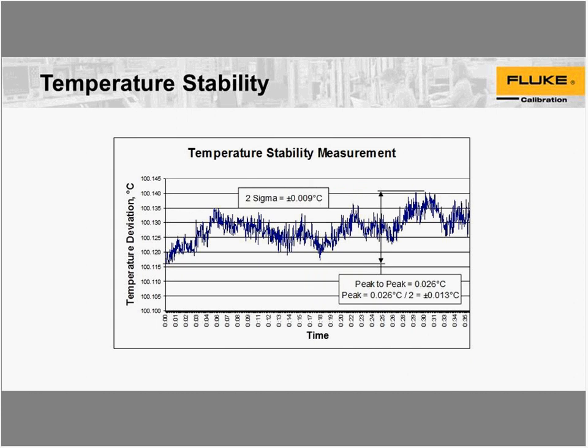The next item here is temperature stability. What we like to do is have a period of time where we can examine the way the controller is operating with data and analyze that in terms of its stability performance. Here you see a sample of data, in this case over 30 minutes long, and for a dry well I like to measure 30 minutes and look at what it is doing in terms of stability.